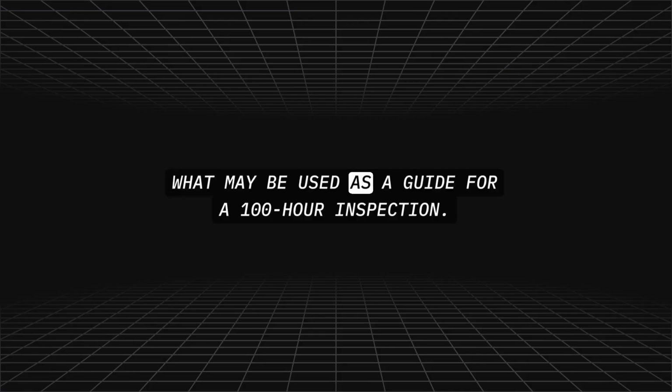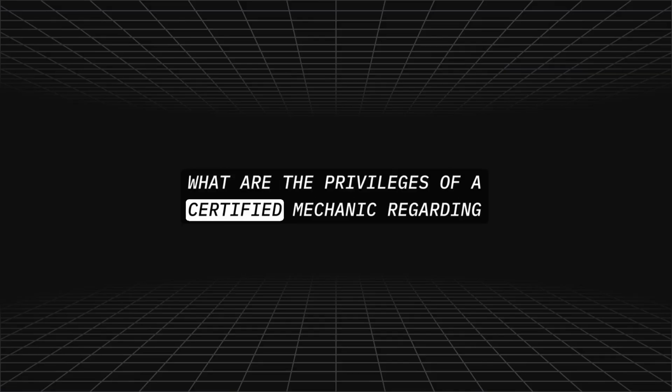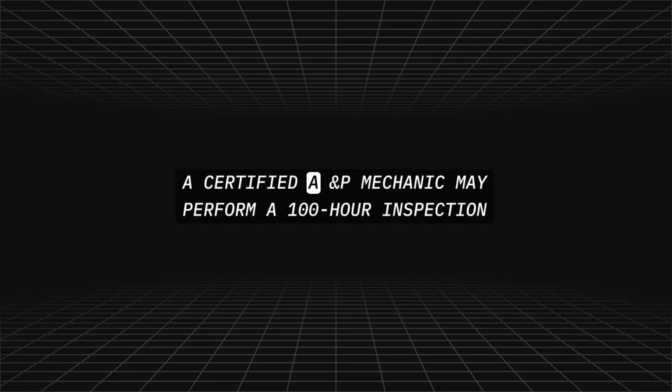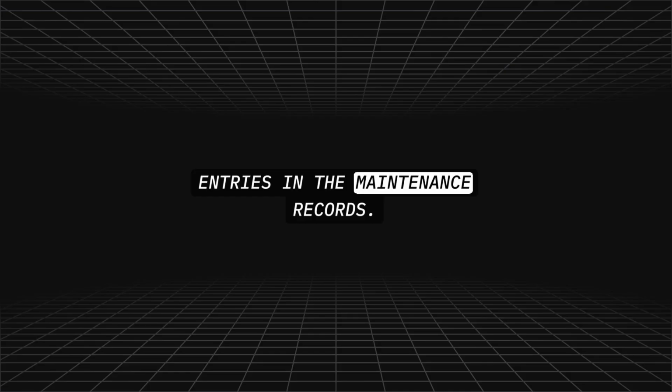What may be used as a guide for a 100-hour inspection? Title 14 CFR Part 43 Appendix D. What are the privileges of a certified mechanic regarding performing 100-hour inspections and returning an aircraft to service? A certified A&P mechanic may perform a 100-hour inspection and return the aircraft to service by making the proper entries in the maintenance records.